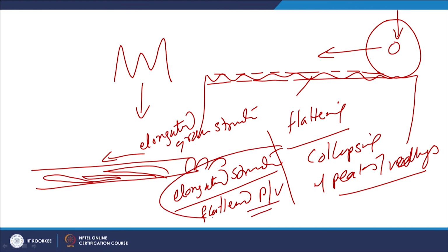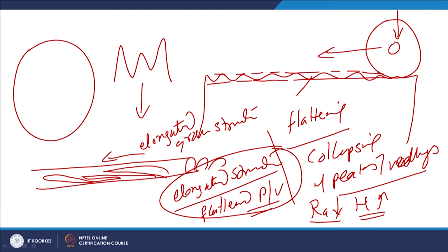Because of these two, surface roughness is reduced and hardness is increased. These are the two main effects observed when burnishing using a large diameter burnishing tool or contour rolling is applied. Both will have similar kinds of effects.